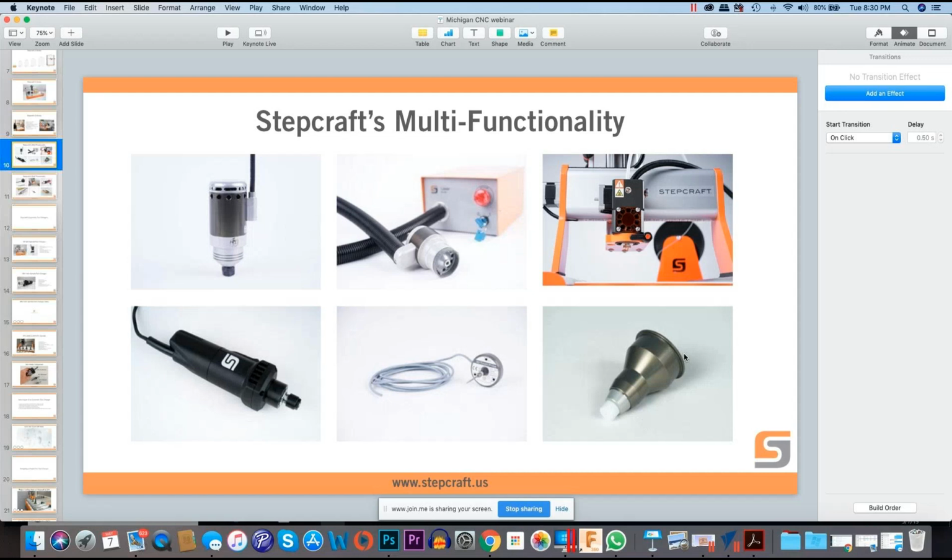I know there's an awful lot of interest in guys putting lasers on their machines. Is your laser adaptable to other people's machines? Yep, absolutely. You can use it. Again, you're using the same PWM signal that you would use for the RPM control to control the laser power, and then you'd have to have a post processor that you use in Vectric that will basically just reassign your spindle RPM and turn that into power. There is a laser post processor that they should have defaulted in there for that. But yeah, it works. It should work with any machine. You just have to wire in the laser control to that signal.